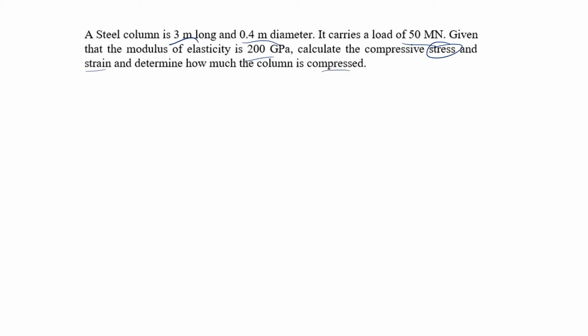All right, so first thing, let's just go with the first thing it asks for, which is the stress. To figure out stress, we're going to use its formula. We're going to have force divided by area. We know the force is 50 meganewtons. Let's change it to the units we are used to. So we're going to have 50. Mega means million, so we have to add 6 zeros to that number. There's the number of newtons.